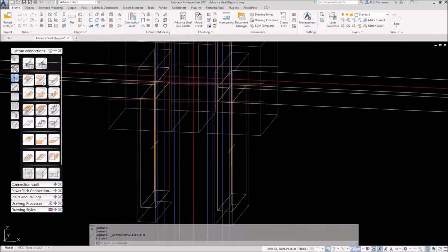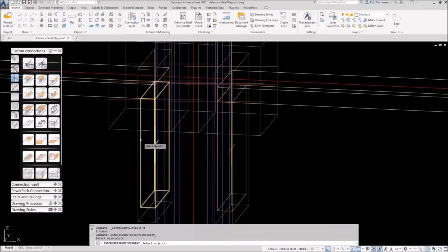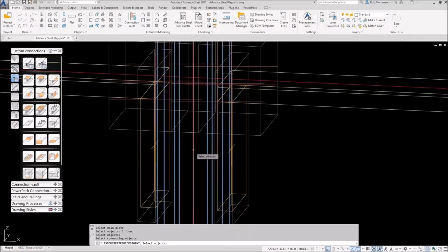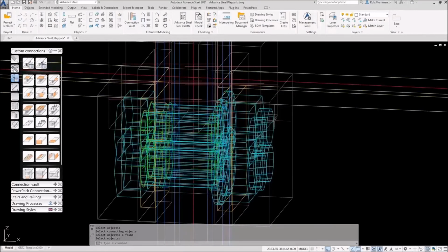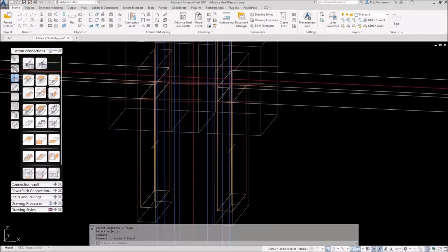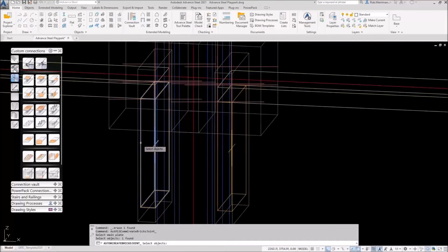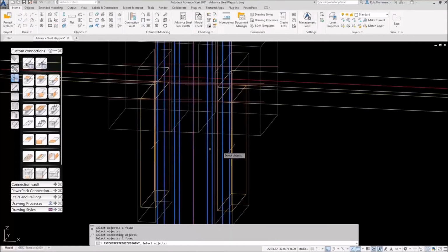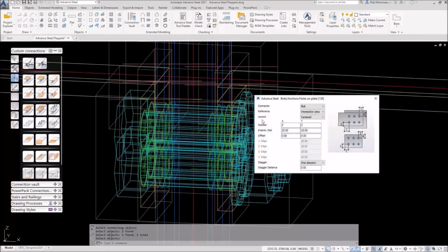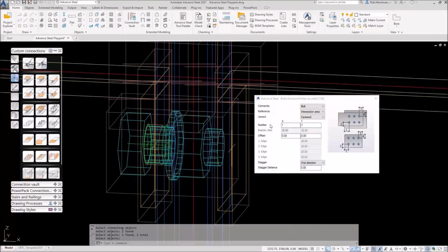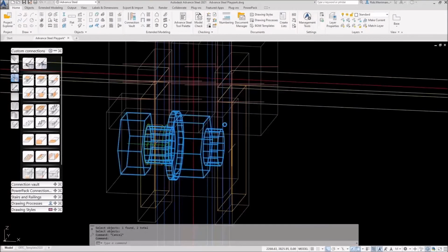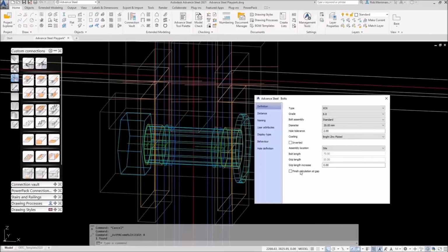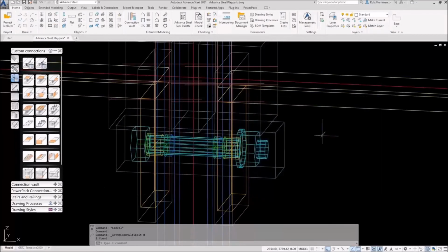And then in here, we're going to do the same, but we're going to do a single and a double connection. So that's the plate, it's connected to that. I needed to do both at the same time. So that's the plate, it's connected to that and that as well, 1 and 1. And then in the bolt here, I don't do finish calculation at gap because it's finding the gap in the box section. And again, we'll just make that an M10.